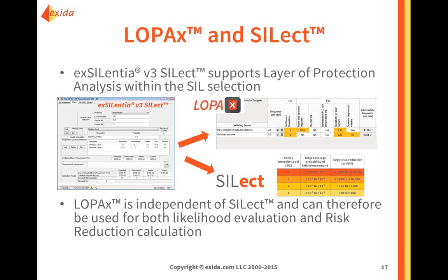We will see that the process hazard analysis tool will allow you to determine hazard scenarios, and those are the basis for the layer of protection analysis. And for those hazard scenarios, you can put in as many initiating events, or as many causes as you want, which could be one or which could be many.